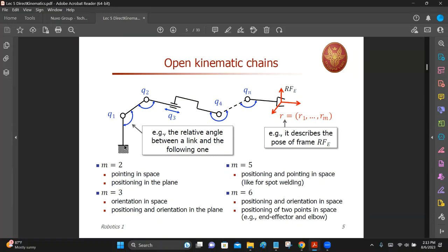So you have to assign a coordinate frame to the base, to the ground. You can call it the earth frame, right? The reference frame. And then at the end of the base, you have the first link. And at that point, you have the first joint. There you define or declare another coordinate frame. And that is for the link 1. So when the link 1 moves, the coordinate frame also moves, right? Because the coordinate frame's function is to describe the position and orientation of that link.